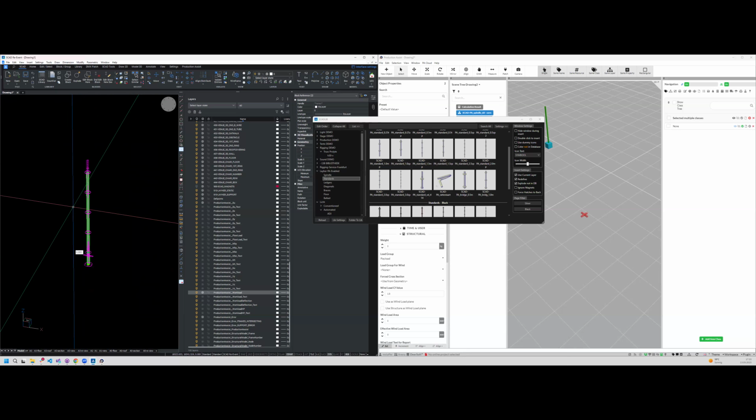There are several commands behind this for using the keyboard. What we now want to do is copy it in the X direction. The command for this is CX and then pressing enter, which will activate the copy in X direction. The easiest way for me is to type in the distance X, so you type in 2072.